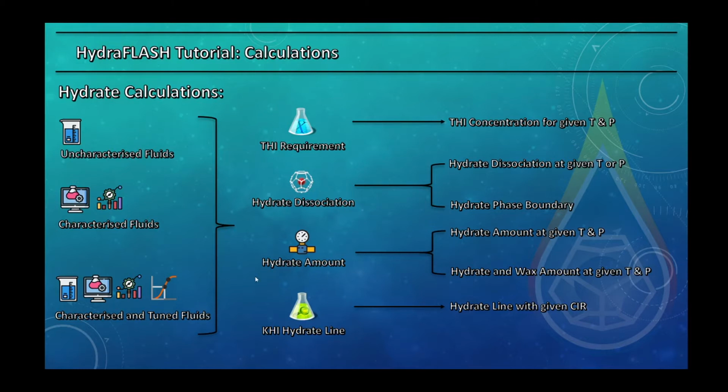The only important thing to remember is that when you are performing a hydrate calculation, water must be in the system. If you don't have water in the system, no hydrate forms. So you need to remember when you are creating fluids for hydrate calculations, you need to add water to the system.